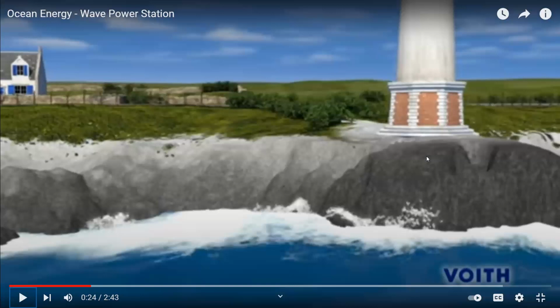Then if you consider the hydroelectric power plants, if the input flow rate of the river is the same as the drained water, then it can produce electricity throughout the day. But that's usually not the case, because in the summer, the rainfall is heavy. In the rainy season, actually, monsoon and such, you have a much bigger rate of water input. But in the winter, water will not fall in as much. So naturally, the incoming water rate in the river on which we're going to build a dam for a hydroelectric power plant is not the same throughout the year.